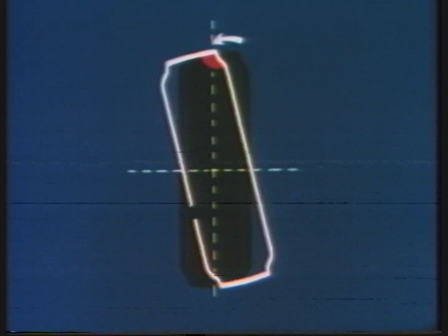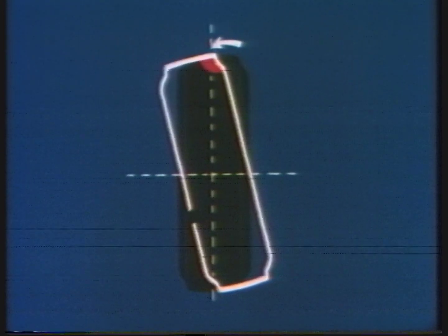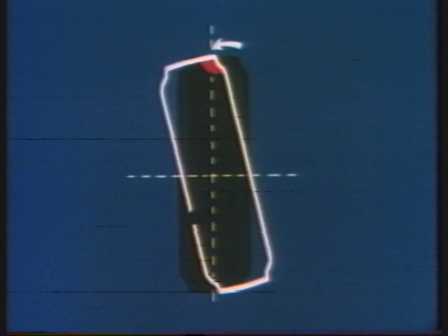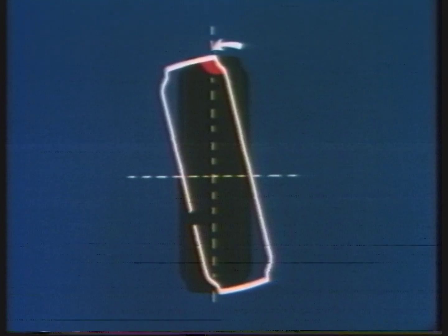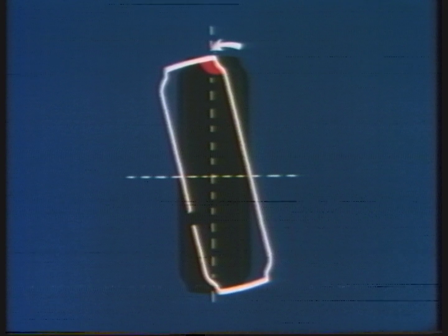Dynamic unbalance is where the heavy point is to either side of the center line, say in the wall of the tire. In this case, centrifugal force acts as before, but because the heavy point is off-center, it also tends to twist the wheel about its steering axis. Combined forces are now at work as the weight tries to swing back onto the center line.